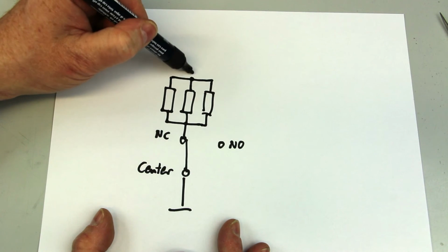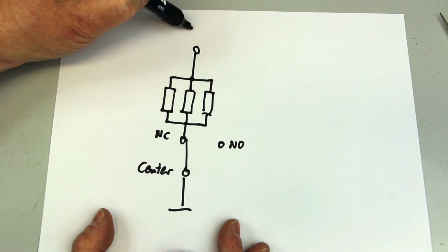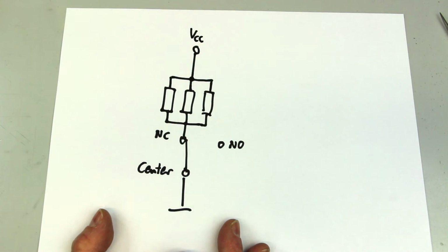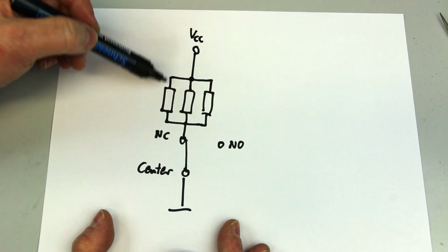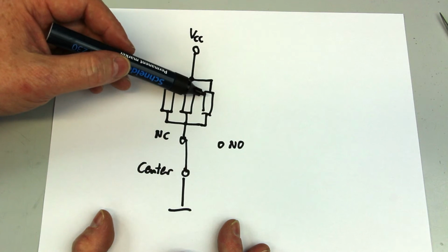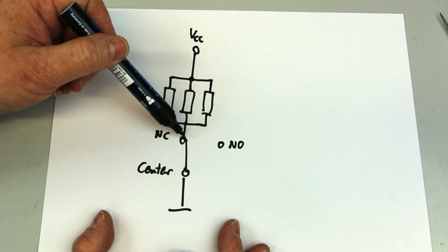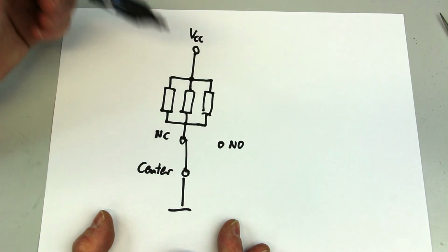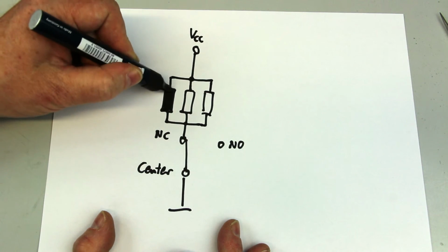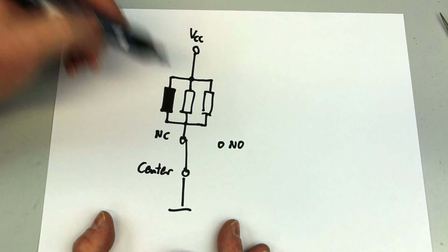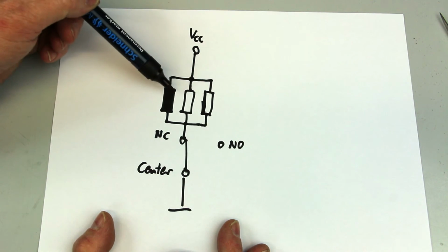That's absolutely a no-go. And you connect them on the upper side to their positive supply voltage. So, as long as the total current through all loads is below 8 amps for non-inductive loads, or accordingly lower with inductive loads, then this is a simple way of switching more than two loads.